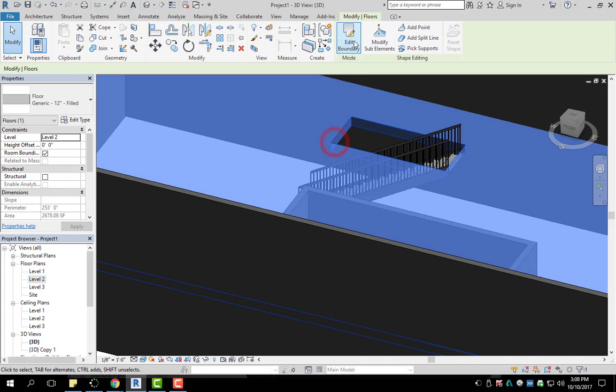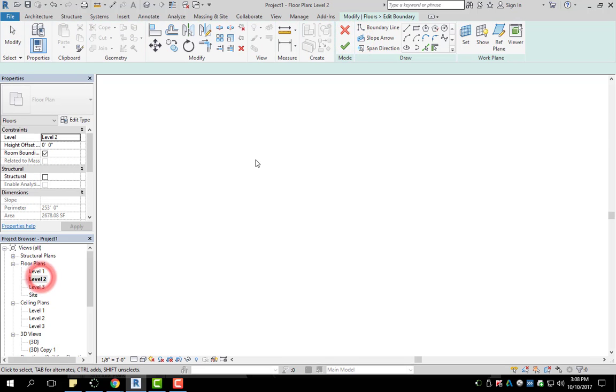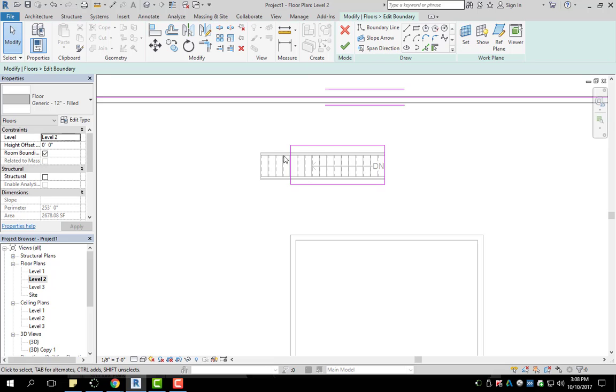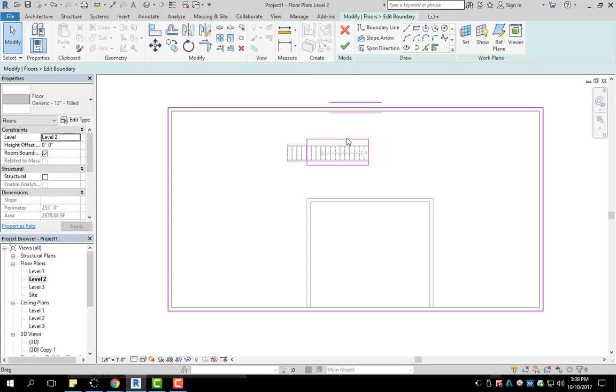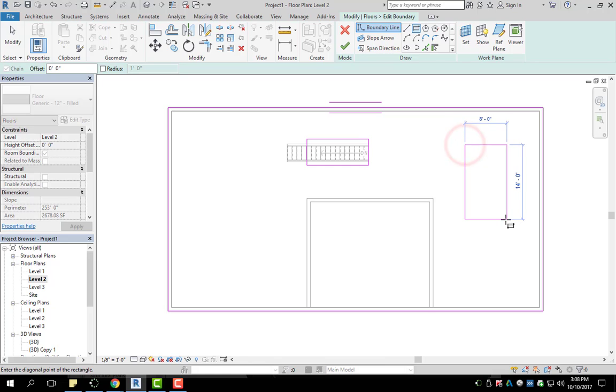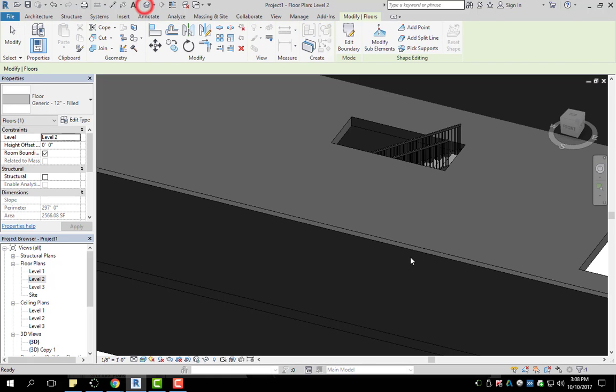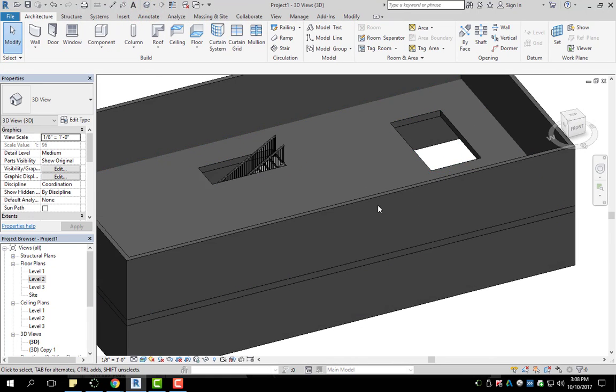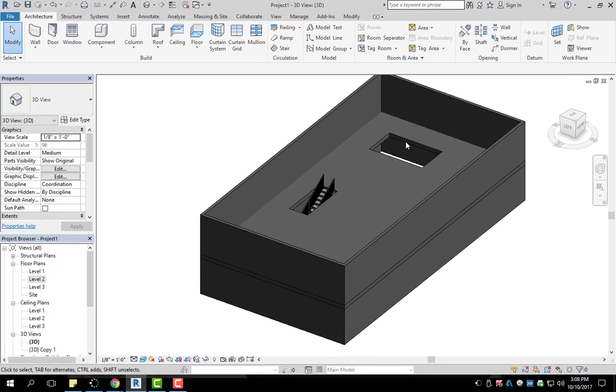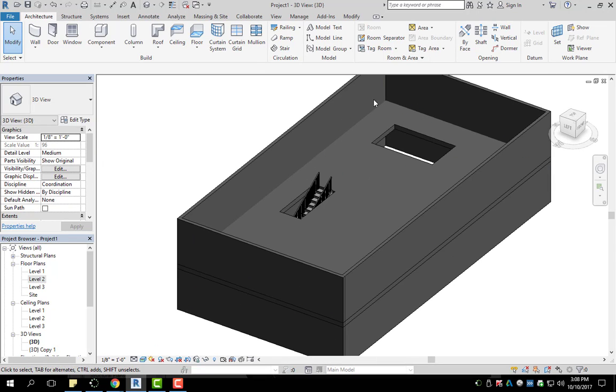So when you do this at a boundary, you can manipulate it in multiple ways. You can do curves and fancy shapes if you would like to, but let's say if I create 2 openings, if I select my rectangle, I come over here, I want this as an opening as well, green check mark, yes. Now I have 2 openings. So as long as you create a shape within the exterior shape, it is going to cut out the shape that is inside the exterior.